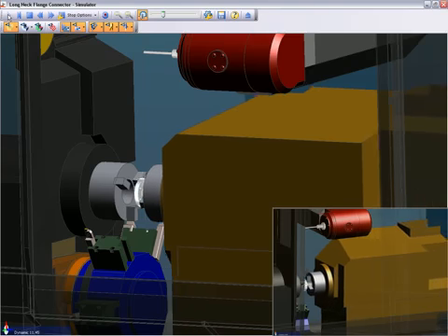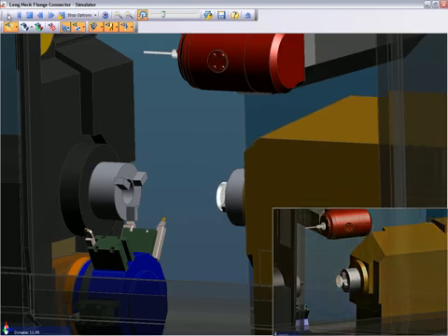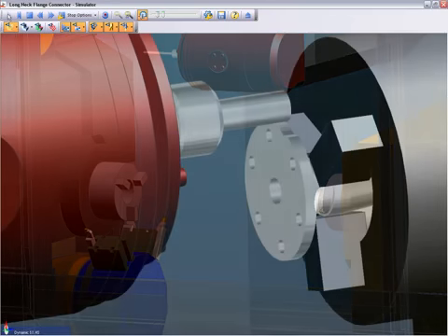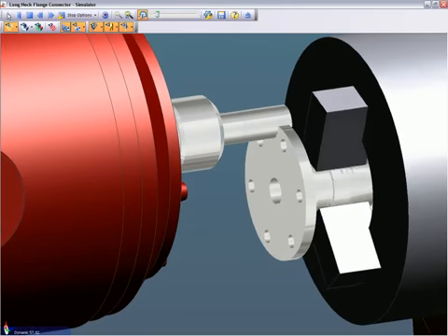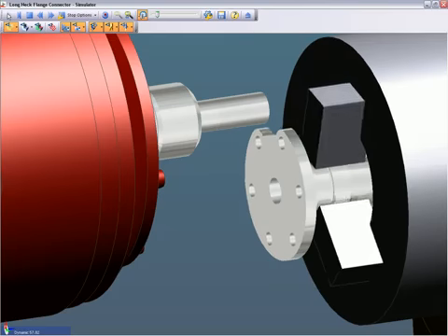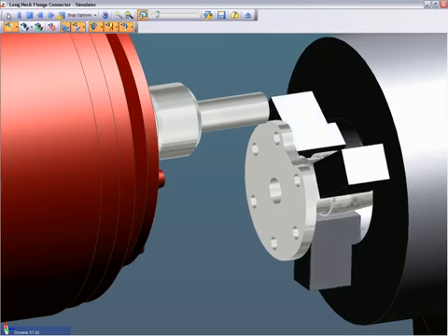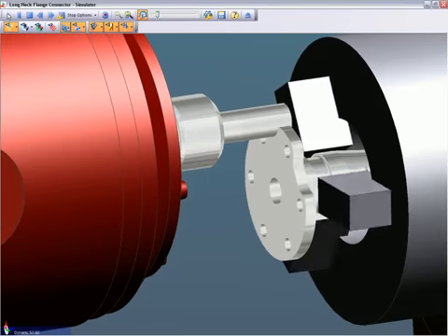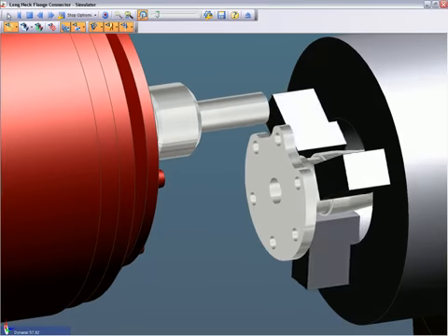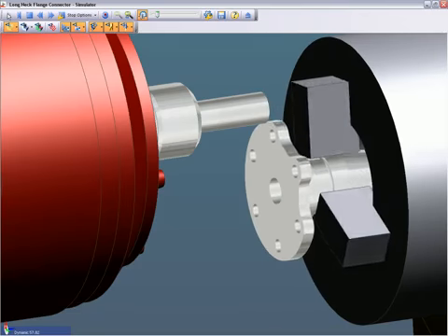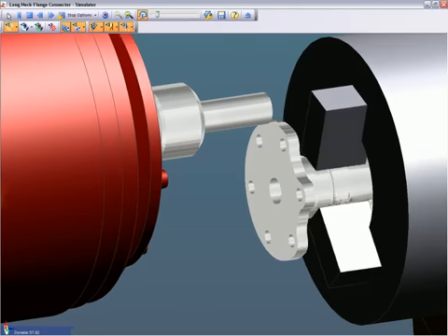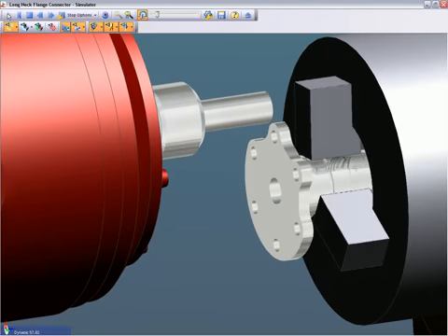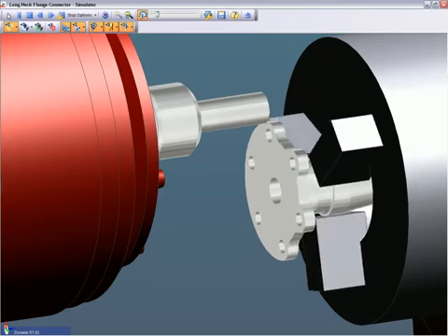So let's review what you've seen in the past few minutes. The solid model was loaded directly into Edgecam without the need for third-party translators. The strategies use the information from the manufacturing features to select appropriate tools and cycles, including the correct speeds and feeds. The decision of which tools and how they were applied is driven by your company's best practice. Simulation confirms the correct method of machining, reducing the prove-out time. The end result is posting of good, clean, edit-free G-code straight to the machine. And at the end of the day, this is the true product of a CAM system.